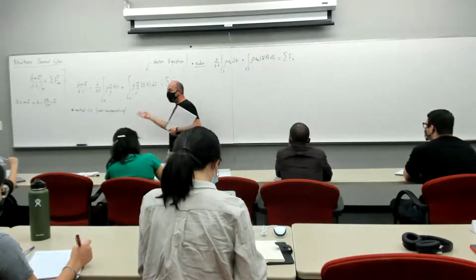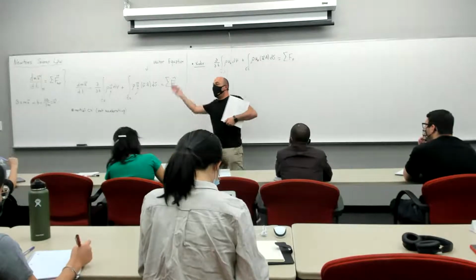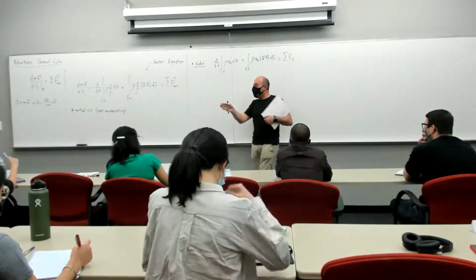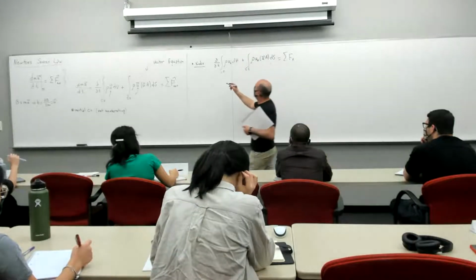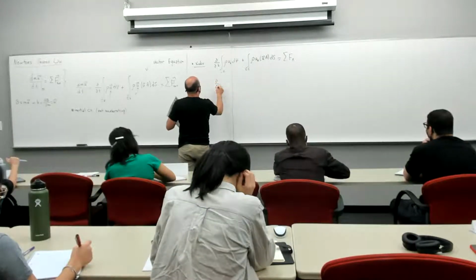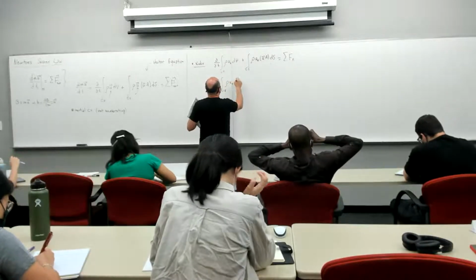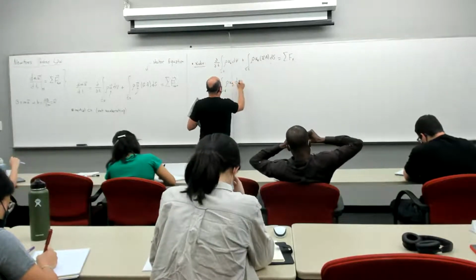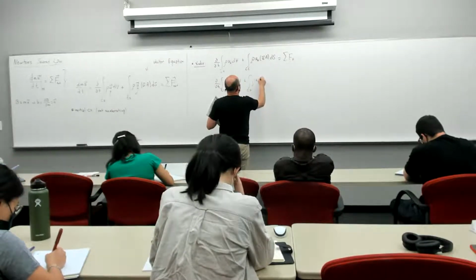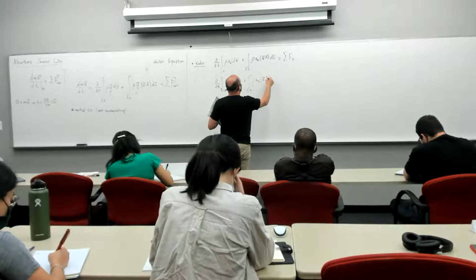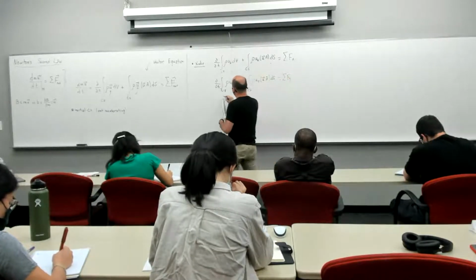It's because it's a vector, and that vector is transported by the velocity vector, and therefore each component is transported in all 3 directions. Okay, so same thing with the y direction, you get d by dt of the integral over the control volume of rho uy dV plus the integral over the control surface of rho uy u dot n dS equals the summation of forces in the y direction, and so on.